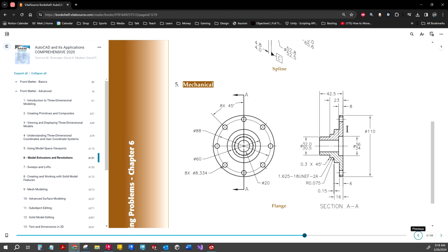And so we have a few dimensions that may seem a little muddied at first, but when you look closer, it's fine. At first, you may think 8 is for the width of the flange, but then you see it doesn't line up, and you realize that actually that's for the hole. So when we're drawing at first, we're going to kind of ignore the hole part in here, and we'll just work on doing the rest. So the actual flange width is down here at 6.